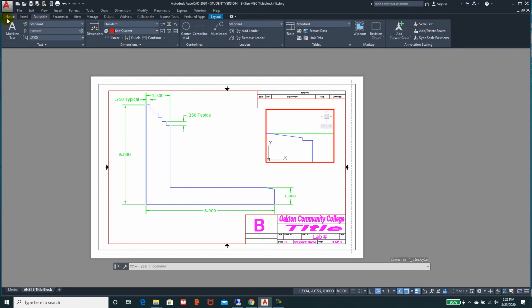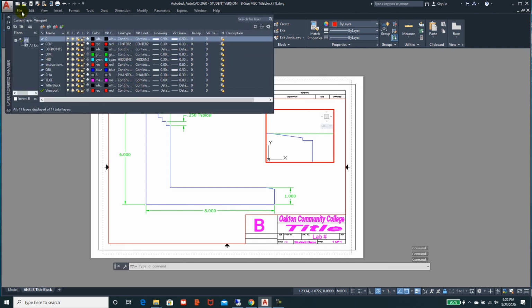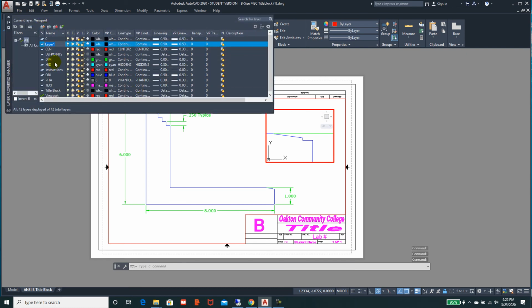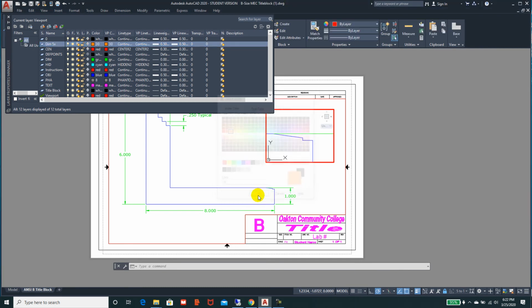So now when I put in the dimension, I'm going to create a new layer. And I'm going to call it Dim2, or we'll call it Dim5X. And we'll give it a different color. So that one's green. We'll make this one orange. And we'll make this layer current.